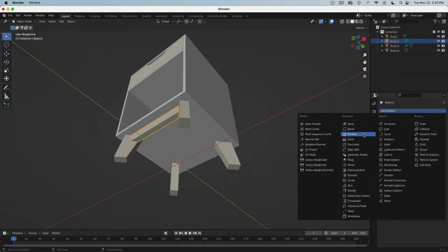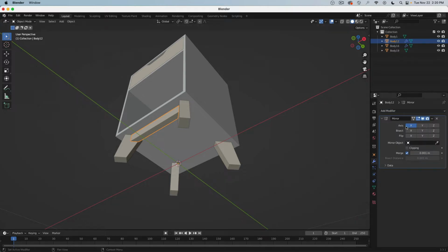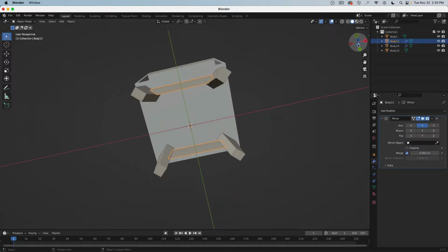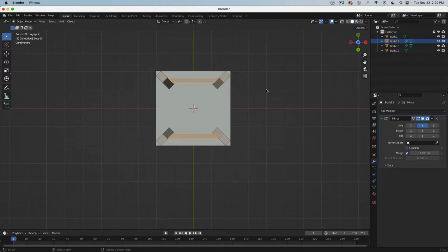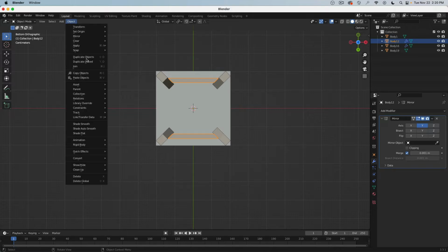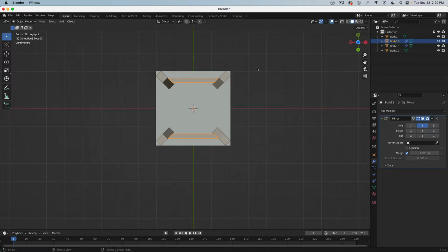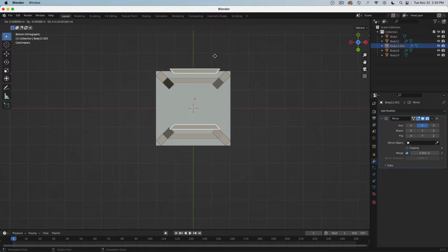And technically speaking, I can even do the same with these pieces here. The only issue here is I can make a mirror along the Y-axis, okay, but I can't really go the opposite side because it is, unlike the legs, not left of the Y-axis, it is centered on it. So if I would make an X mirroring, it's just right there. What I can do, however, is make a clone. So to make a clone, this is actually a duplicate linked. The control is Control D, and then now you can move around, press R to rotate, and then type in 90 and enter.